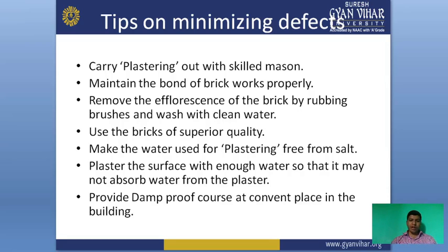Remove the efflorescence of brick by rubbing with brushes and wash with clean water. Before using the brick, we have to wash the brick with clean water. Use bricks of superior quality, which means good quality bricks should be used. Make the water used for plastering free from salt. While using water in plastering, we have to ensure the water is free from salt.